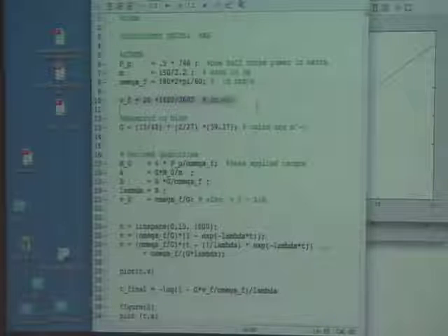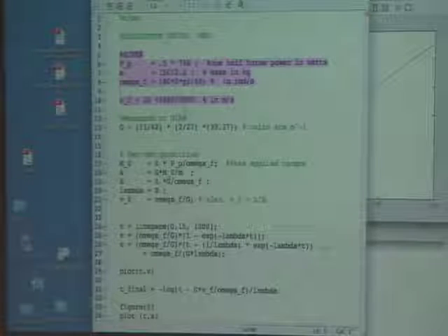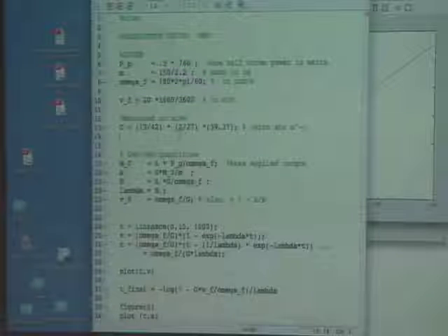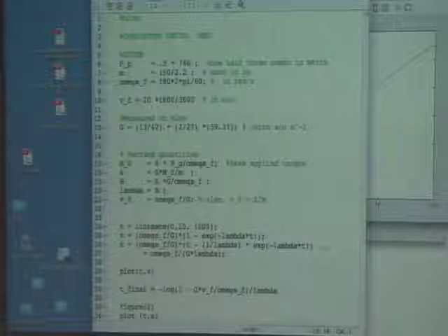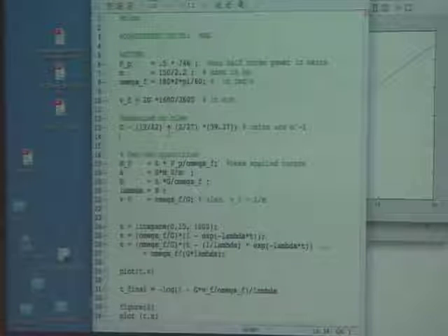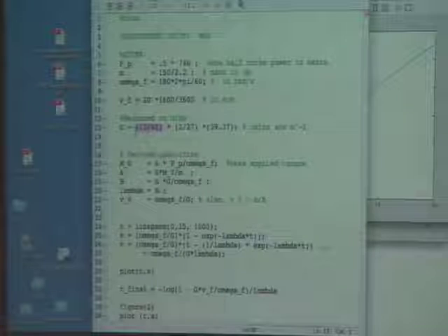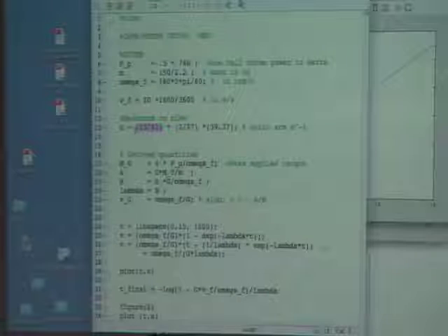So these were the numbers that we were given, from which almost everything else follows, except for the things we measure on the bike. On the bike, we measured all these radii. The answer was actually the ratio of 3 radii. I've divided it up differently here and put it in the ratio of 2 radii, and in the ratio of gear teeth, standard gear teeth ratios.